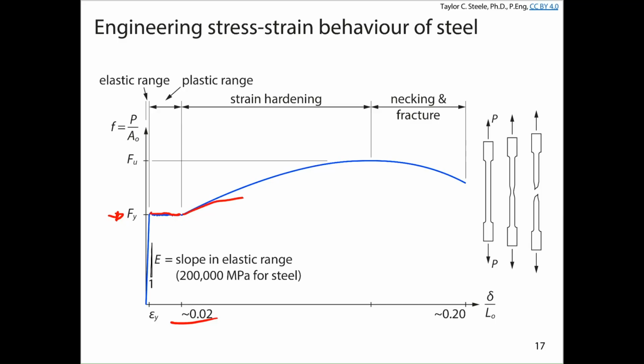So basically all I want to really communicate here is there's an important property, Fy, that tells us when we're going to exceed the linear strength limit of the steel. Even after it yields, we tend to never lose a significant amount of strength, even if we stretch the bar by 100 times the yield strain of the structural steel. At a certain point, we will develop a peak force or a peak stress.